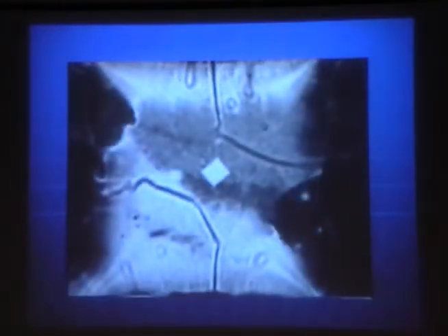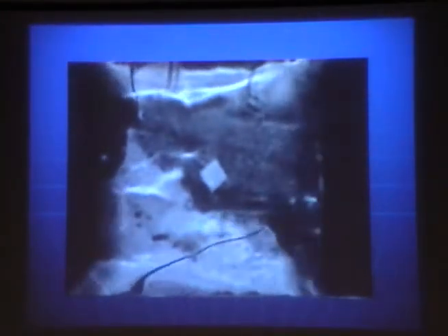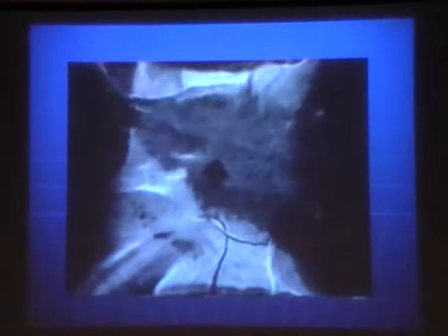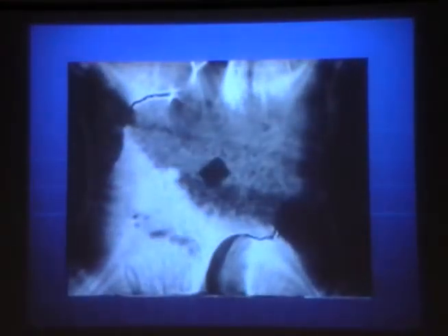The central region was processed by atomic force microscope. And we cannot see individual domains because they are too small to see. Or in other words, we intentionally used a higher numerical aperture objective lens to reject diffracted light. That way we can have a uniform bright state and dark state. And these bright and dark states are indefinitely stable without any bias electric voltage.